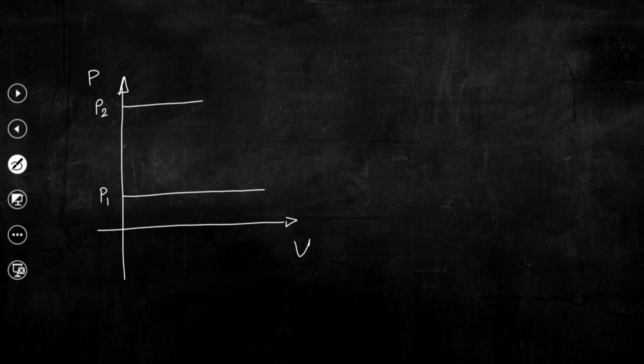We need to increase the pressure of the working fluid from P1 to P2. If we use single stage compression, then we can certainly develop the pressure. So, this is 2, say this is 1 and this is 3, and 2 to 3 is PV to the power n equal to constant.